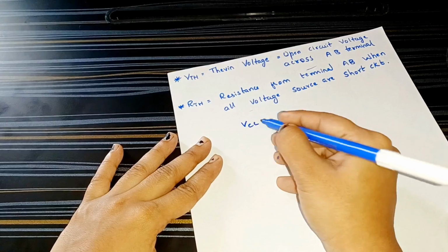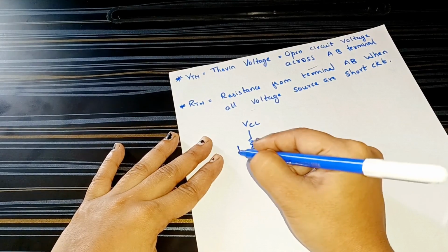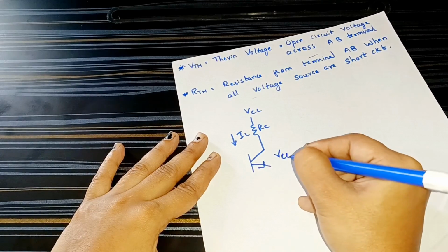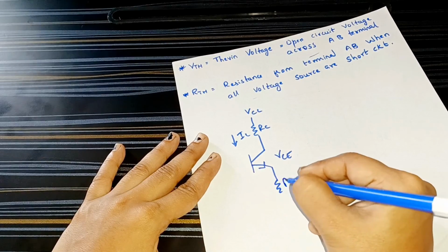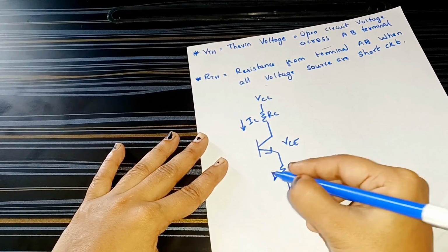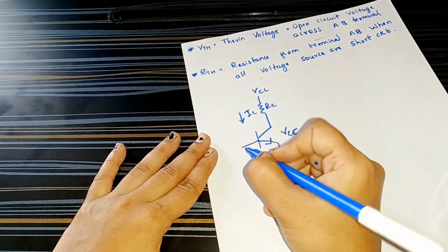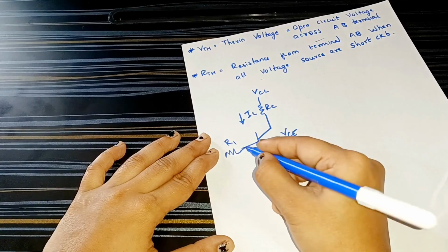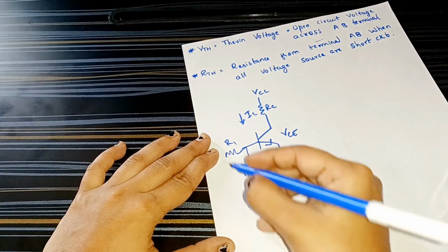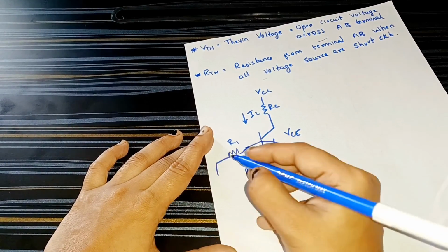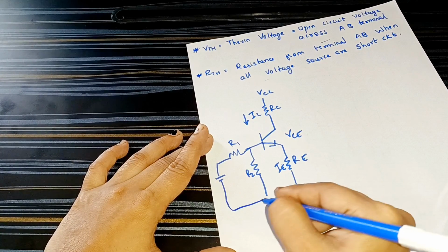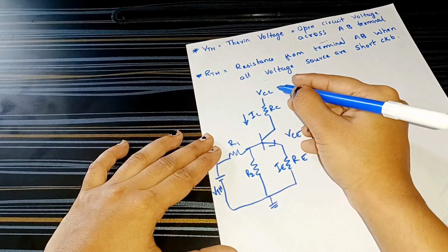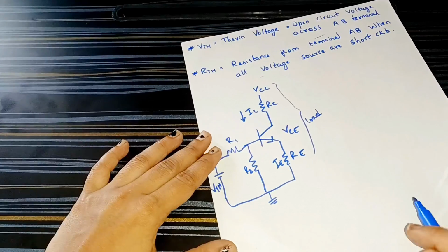We keep VCC, the resistor RC which carries the current IC, the voltage VCE across the collector and emitter, and the emitter resistor unchanged. We convert the part with R1 and R2, taken as the load, into the circuit connected to VTH.